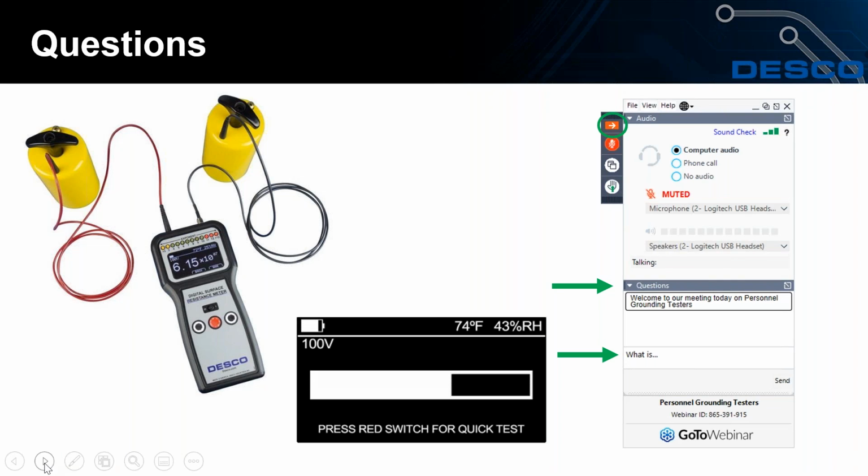It's still going to be over the limit, but I don't have to wait for the whole time. That also has to do, again, with that accuracy number. The reason it's doing this is because it takes a lot more time to make a more accurate measurement as that resistance climbs over 10 to the 9th, over 10 to the 10th.